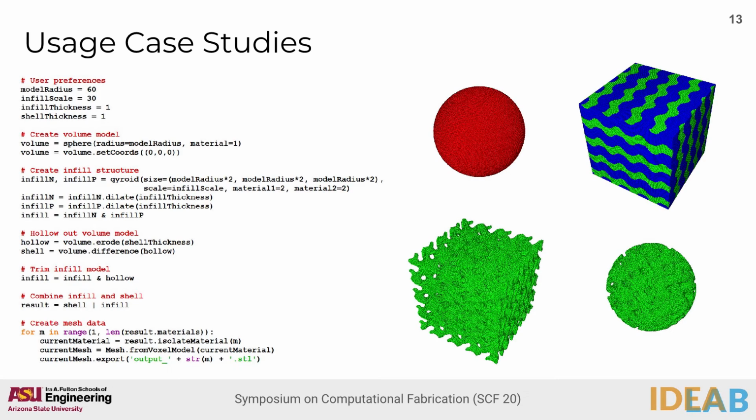The code shown here illustrates using the VoxelFuse framework to generate the target volume, generate the infill structure, find the hollow and shell regions of the model, then combine all of these features to form the final multi-material model.